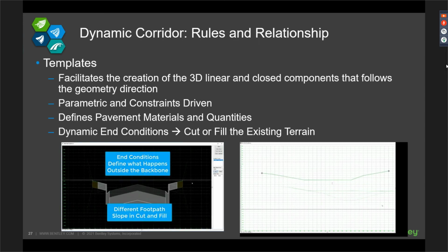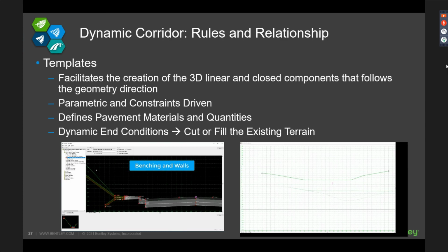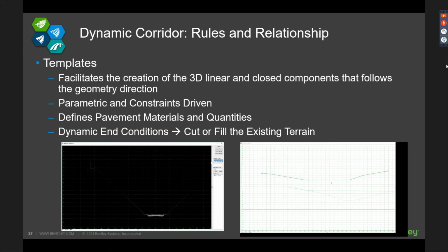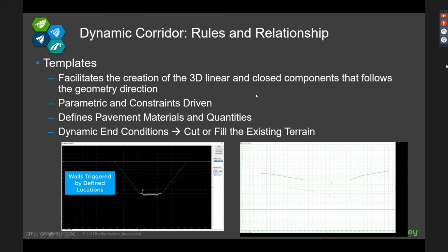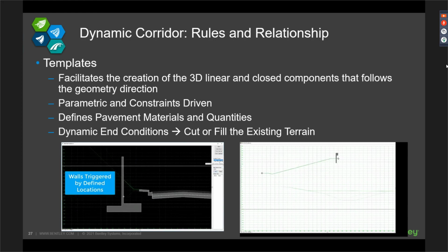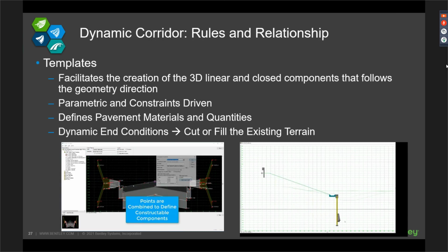But of course, I have to be honest, because the technology behind Civil 3D and ORD are very much different, the sub-assemblies or assemblies that you have created in Civil 3D, you have to recreate them as a template. The template, which is what you're seeing on the screen, is the equivalent of the assembly and the sub-assembly in Civil 3D. So again, just export them into LandXML, then import them inside ORD.